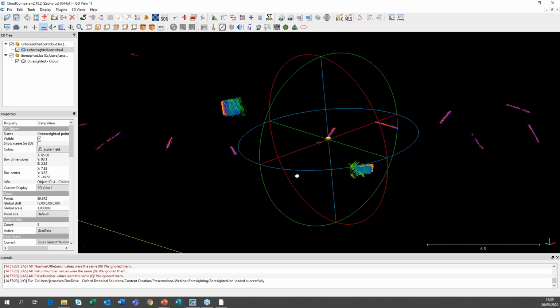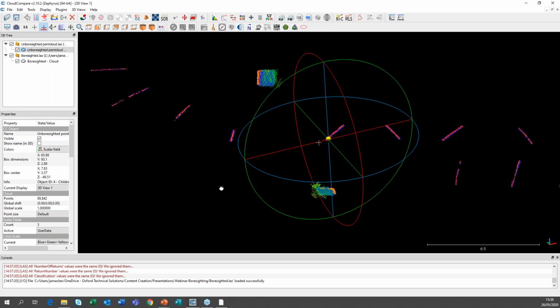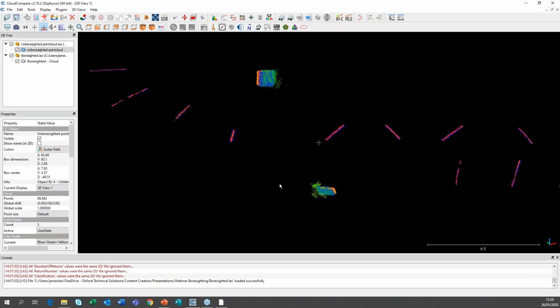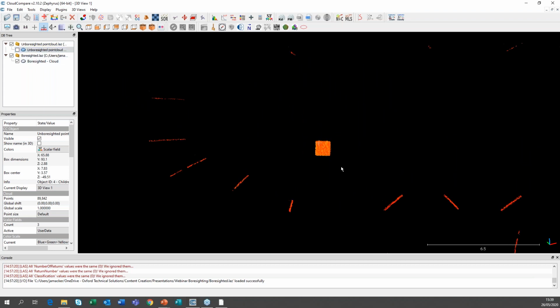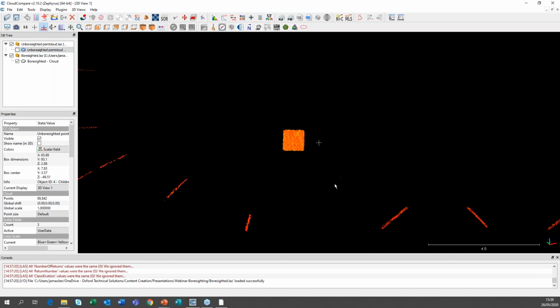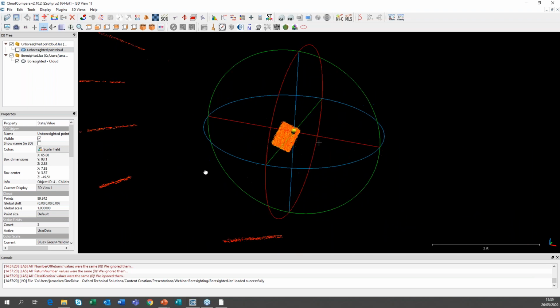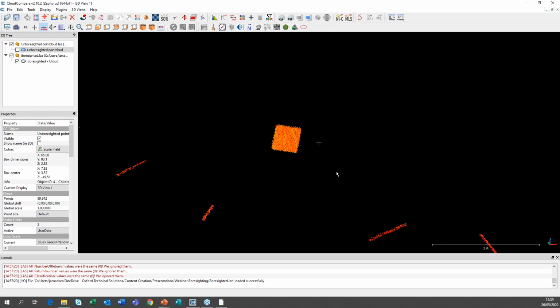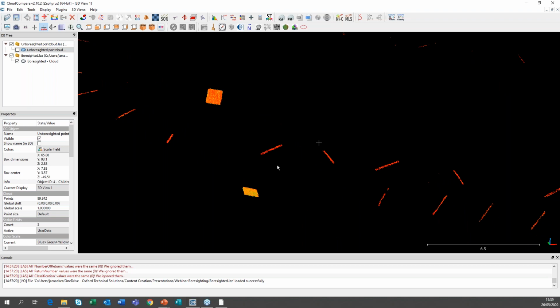And even getting the 55 is quite difficult. So getting within one or 2 degrees is about all you can do, and you need to really get 0.1 degrees for the best data, where your inaccuracies are coming in then just from the LiDAR device itself or the INS inaccuracies.